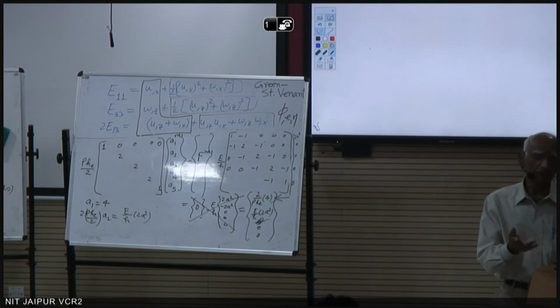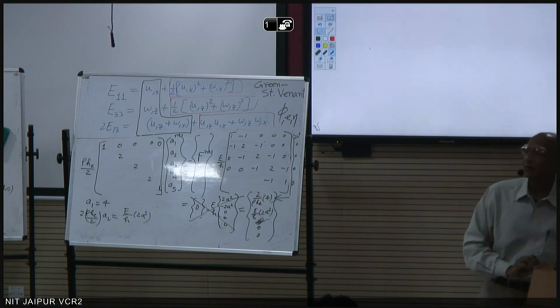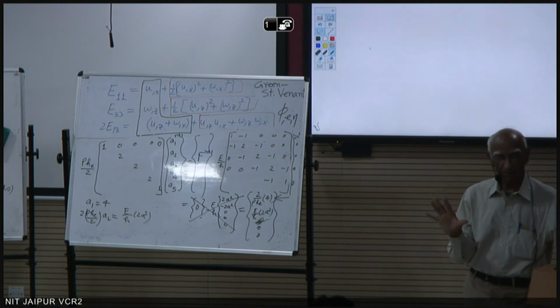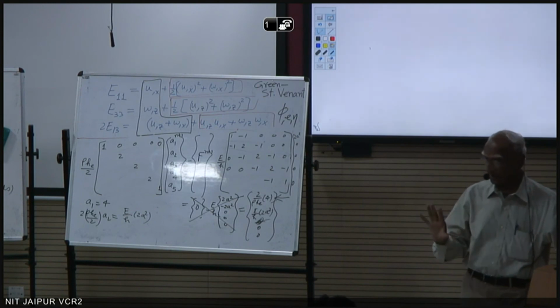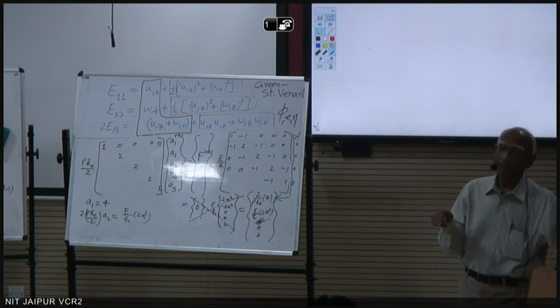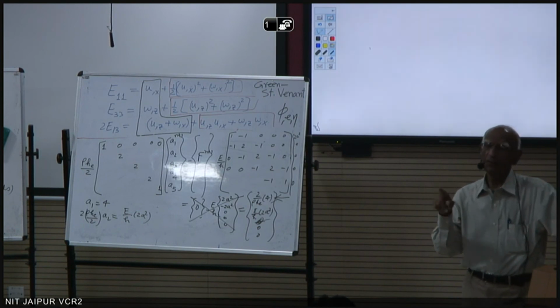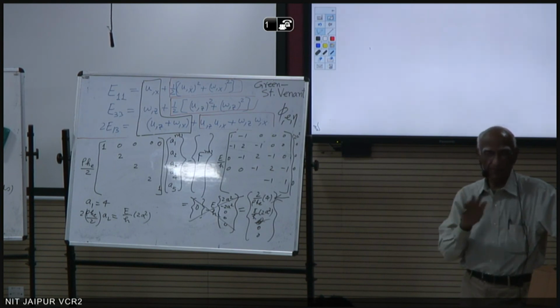For that, you need to write a code. So if I were doing it, I will do by hand for 5 nodes. Really do by hand. I will solve the equations by hand. Then I will write the code and compare the output from my code after every time step. 1 time step, 2 time step, 3, 4, 5.